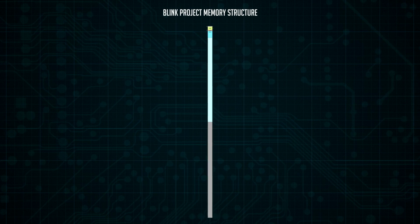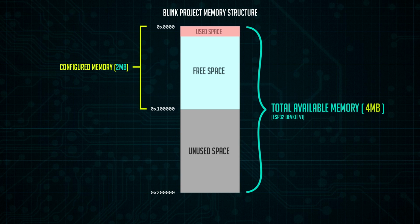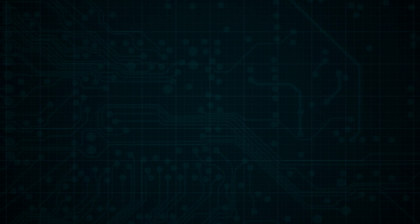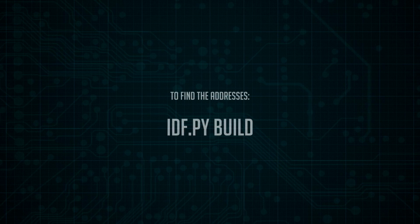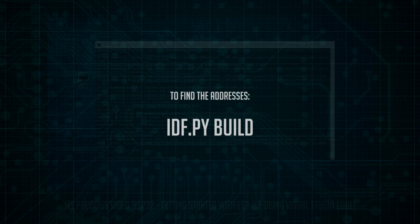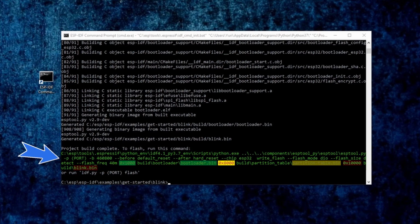Since we haven't changed this project's configuration, we have only 2 MB of free space to use. We'll get into more details in the next video. To find the addresses for our project, we can just run the command idf.py build. Remember that huge command line from the first video? It is there where we can see the name of our binaries and their memory addresses. They can vary depending on how you structure your project.